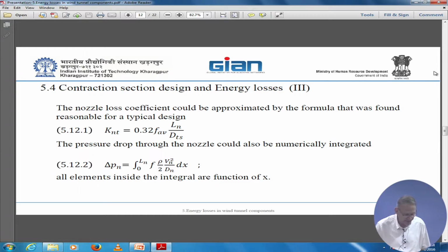Typical porosity of screens we are using is between 0.5 and 0.8. What we usually do is have a series of screens, starting from the rough ones and ending with the delicate ones. In Tel Aviv, I put 3. Also in Jerusalem, I put 3. I have not yet made turbulence measurements there, but it looks smooth anyway. We'll see shortly what happens there.